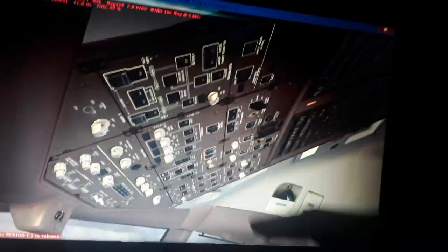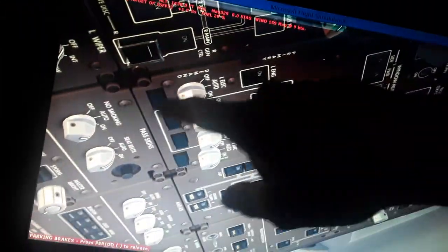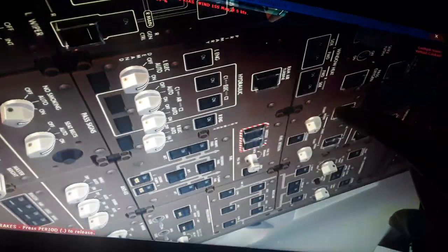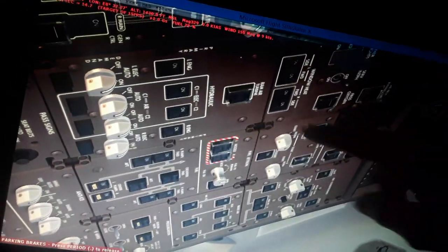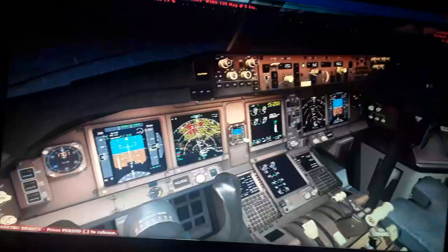So you can see inside the cockpit, the overhead panel, we have the electrical, as I told you here, the left and the right engine generators, the backup generator, the APU, the flight control computers, the ADIRU, the air data reference unit, the hydraulic system, here the pumps, the engine driven and the pressurized air, the fire extinguishers, the passenger oxygen, the ram air turbine, the fuel system. We have the fuel tanks, left wing, right wing, center tank, crossfeed valves, cabin pressurization, and the bleed air system, and the wing and engine anti-ice. So you're gonna see all these systems. I'm gonna start the engines later.